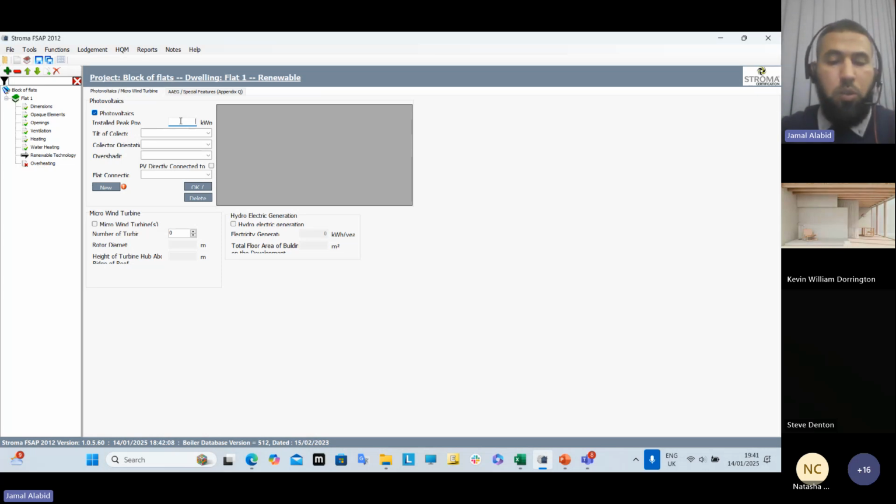So say 250, or you calculate all of them. Really, it depends on the size, 250 each panel, how many panels you've got, times this. If it is 10, then the inclination, the tilt, depends if it's installed directly on the roof or not. Then the orientation, let's say ideal orientation south. Shading, modest or no shading.